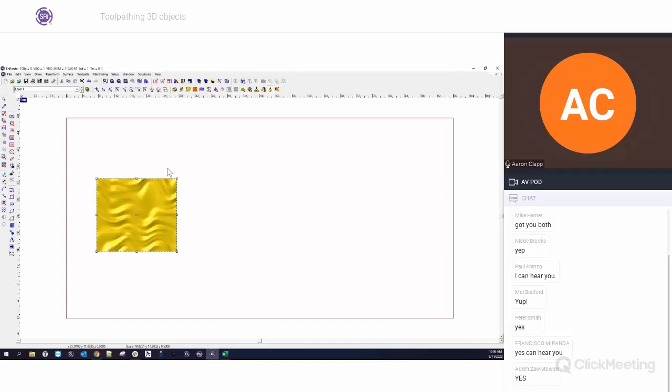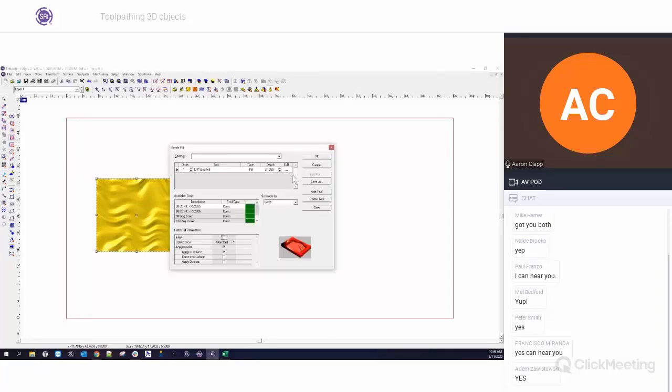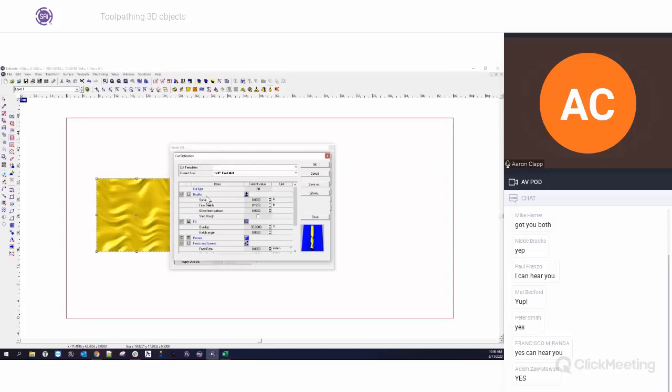If I go from top to bottom, I'm going to end up with a lot more up and down movements. And so if I can prevent as many up and down movements as possible, it'll help me cut out that object a little bit faster. So in this case, I'm going to go from left to right when I apply my hatch fill. So I really don't have to do anything. My hatch angle, I'll just leave it at 0.